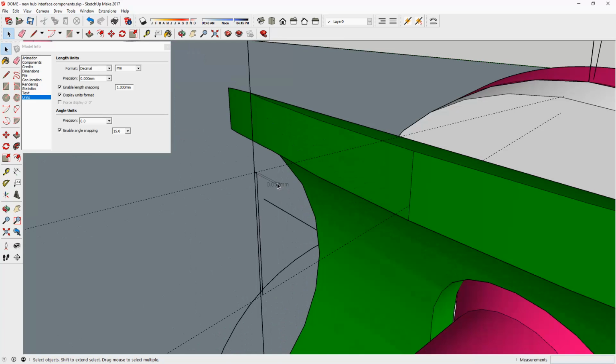That was just to show that SketchUp does measure and draw very, very accurately. Whereas when I was banging on about poor old SketchUp not being able to do this sort of thing, it was my settings, because I don't need to know the fractions of a millimeter generally, and therefore I set my precision to 0 with the increments of 1 millimeter. You'd have to look at my other videos about that, but there we go.